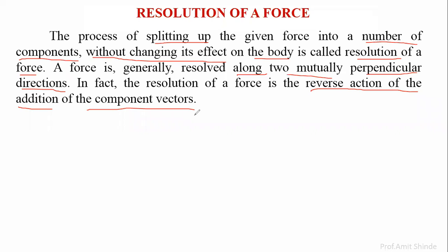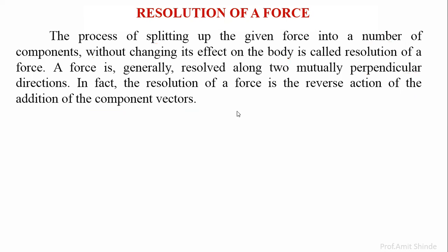It is the reverse process of composition. Resolution means splitting up into a number of forces. If a single force is there and we are splitting it into two components, it is the inverse process of composition of force. Now let us see by a simple example how to resolve the force. This force F has a magnitude of 20 kilonewton and makes an angle of 30 degrees with the horizontal, and we have to resolve it into components which will give the same effect as that given by this single force.